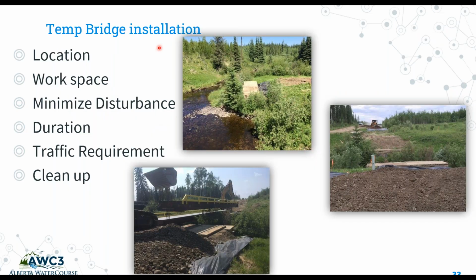Temporary bridge installations. If you have a crossing that requires temporary access, you'll want to think about the location of the temporary bridge. Do you require workspace? Again, you want to try and minimize disturbance. What's the duration of the bridge that's going to be installed? What's the traffic requirement? Is this for large production or log hauls or mining, or is it just for pickup access? And you'll want to consider cleanup.